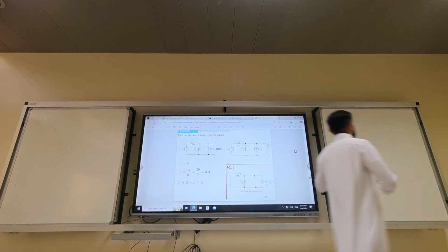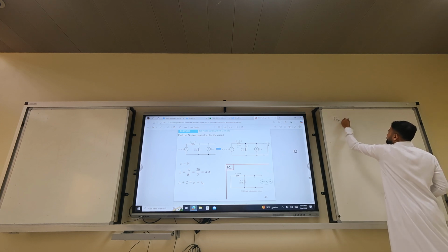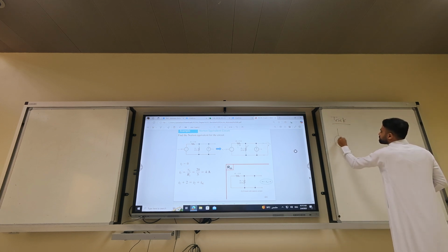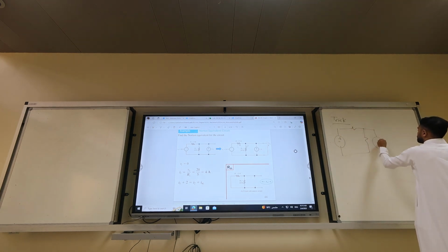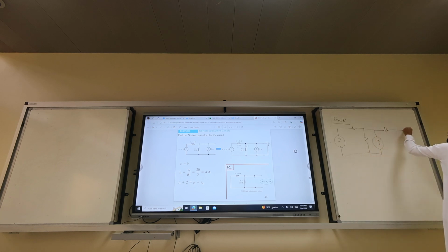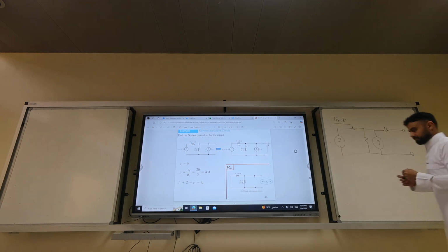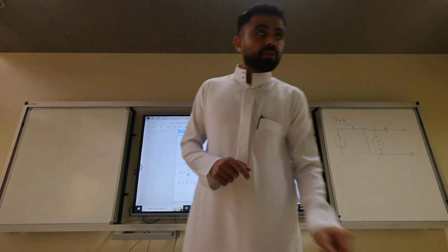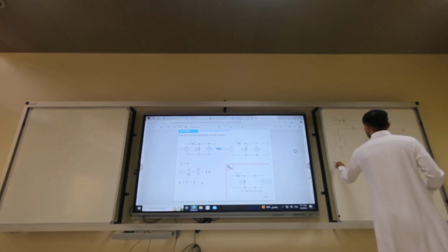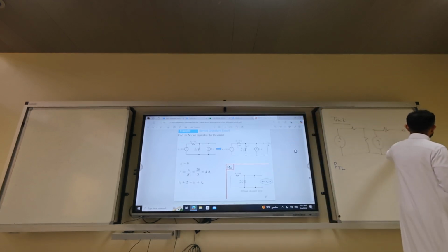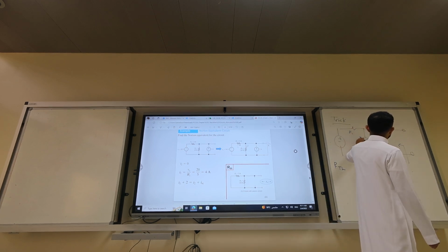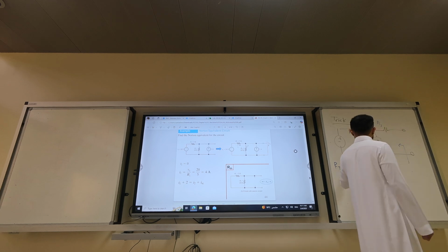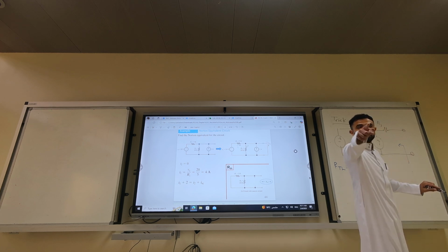Let me explain this trick. Okay? Set this circuit. I said if you add a resistor here, will R Thevenin change? Of course it will change because you're looking here, right? So R Thevenin will be this resistor, let's call these R1, R2, R3, so R3 in series with the parallel combination of R1 and R2.